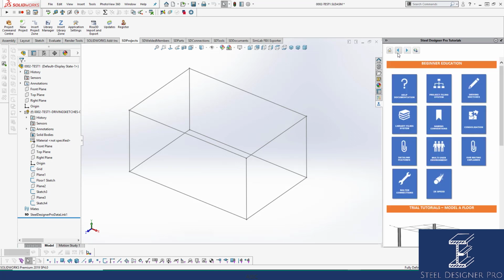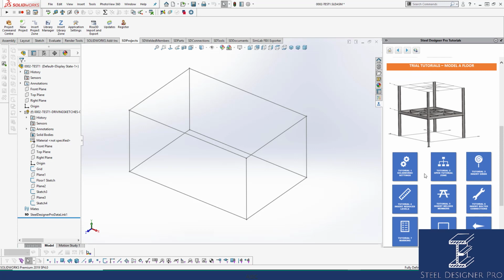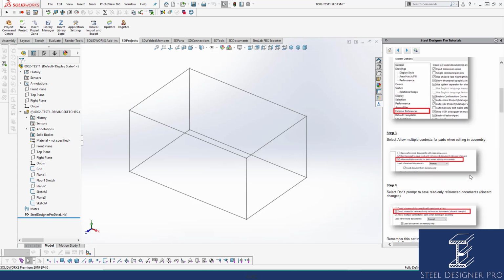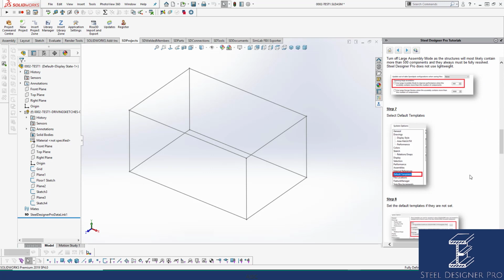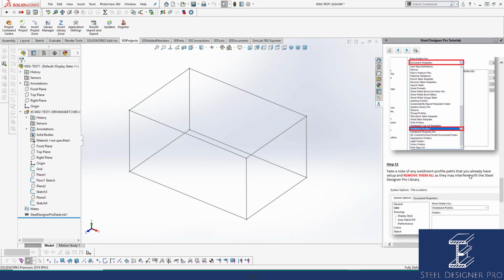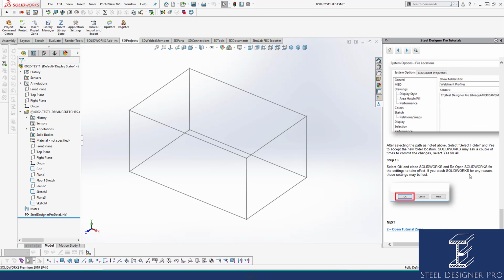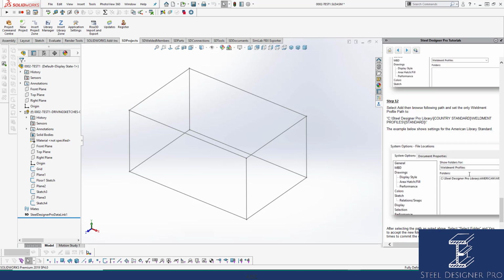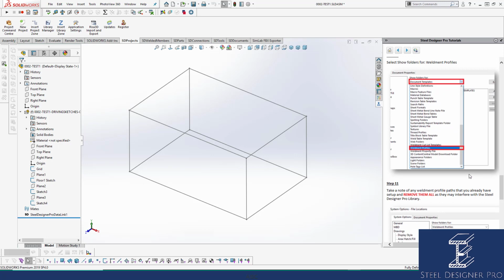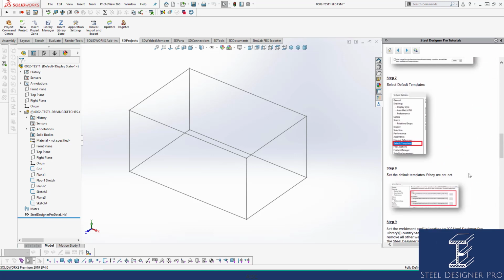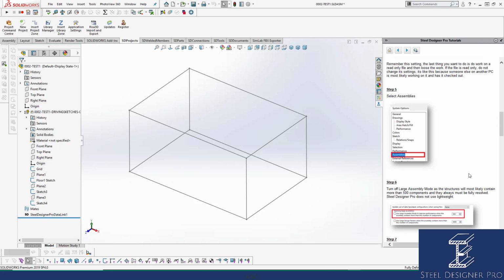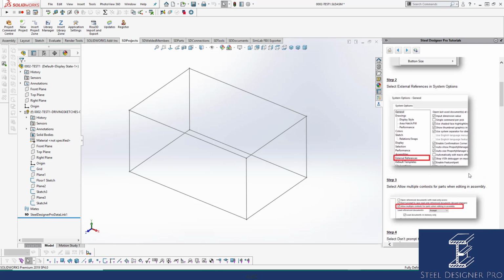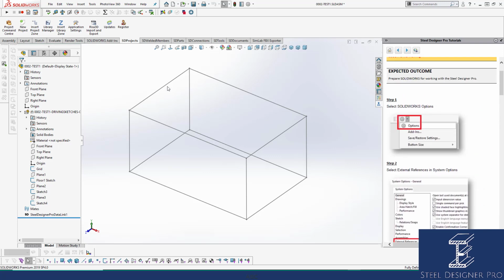So if I go over to our training here, where are we? Project filing system. We'll come down here and have a look. SolidWorks settings. So in here you can see that we cover it. One of the steps, I think we do. We probably don't. But you should be aware that by default, it's not covered. Yep. By default, it collects the mass of hidden bodies and components, so you want to turn that off.